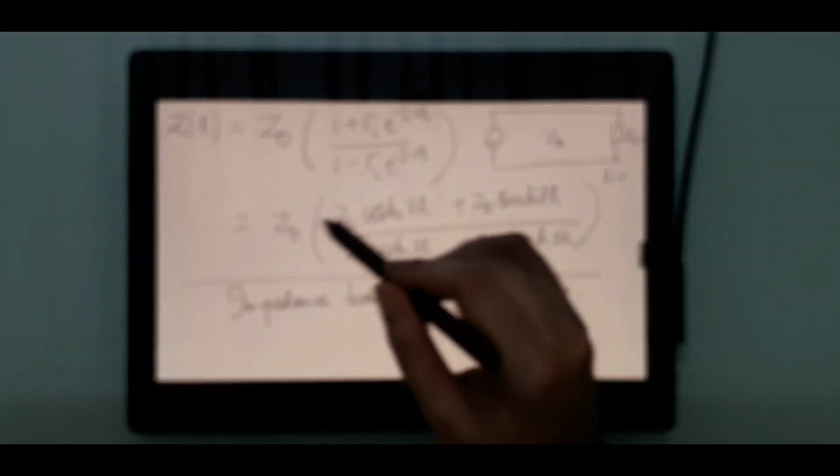in this transmission line arrangement, when L is equal to 0, the impedance is ZL. But at any given point L, the impedance is a function of ZL as well as Z0. So with length, the impedance is also changing. Now this is a very interesting phenomenon which you don't get to observe.